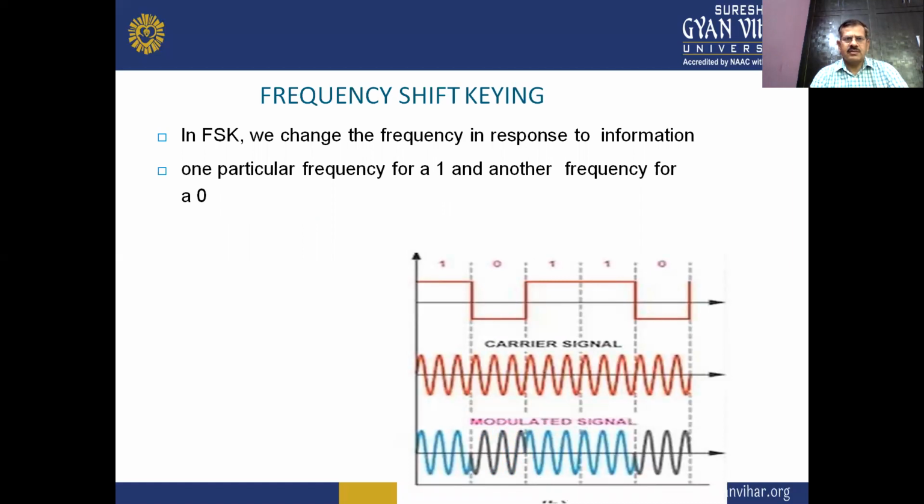The next one is frequency shift keying, FSK. In FSK, we change the frequency in response to information: one particular frequency for a 1 and another frequency for a 0. These different waveforms represent the frequency shift keying modulation technique.